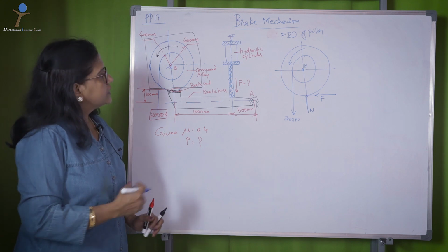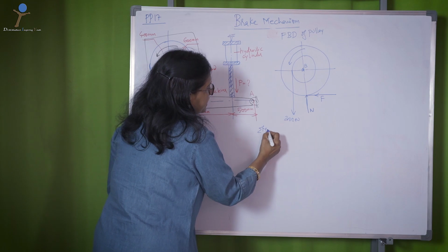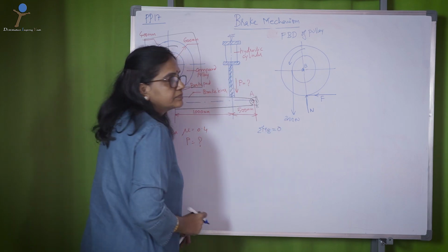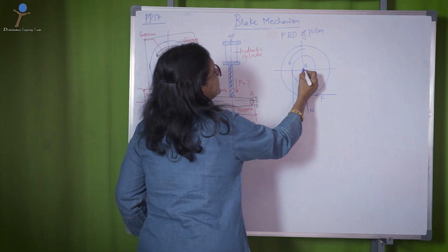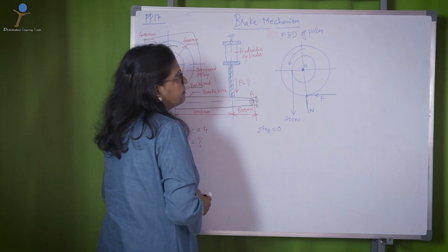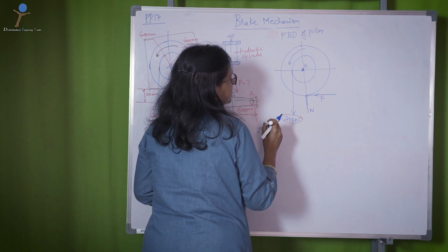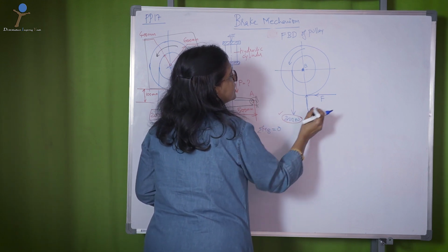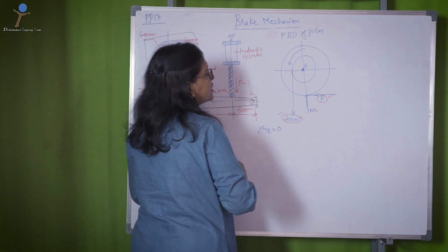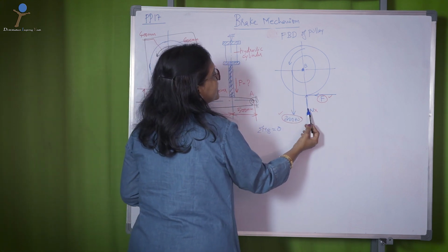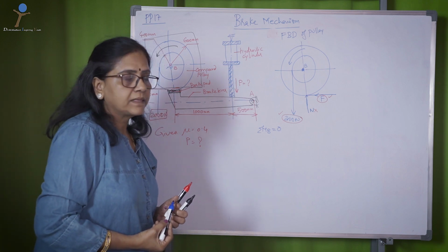So you have three forces acting on this pulley. Simply take sigma MB equal to 0, the moment about B. The force 2000 will contribute to the moment, and force F will contribute to the moment, and N does not contribute to the moment as it lies on the same axis as the moment center.